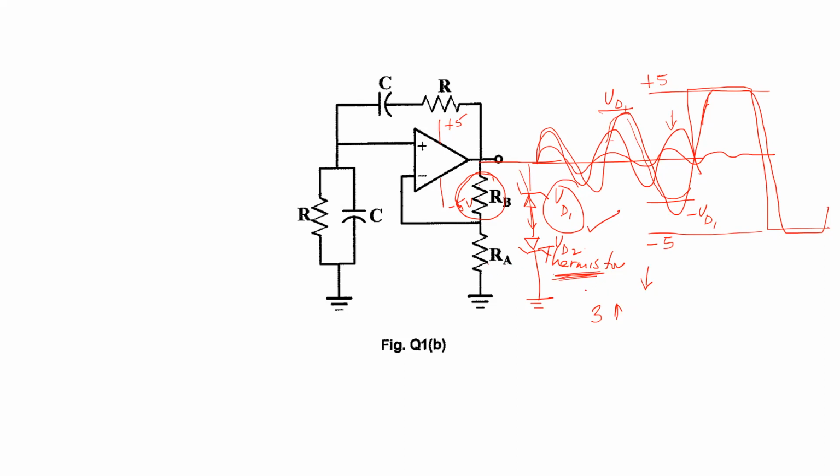So if you need a 1K thermistor or something, a 5K thermistor is a little bit harder to find. If I say they are working between plus and minus 5 volts here, I'll stabilize the value between, let's say, plus and minus 4 volts for argument's sake. I could get a pair of 4 volt Zener diodes and put them in here and get the stabilization working.